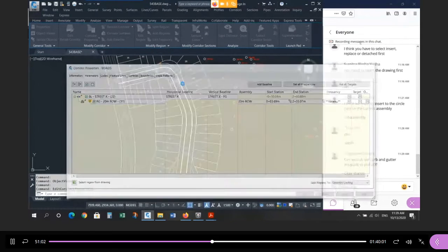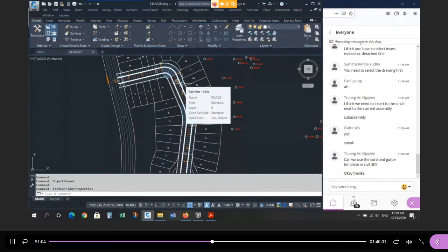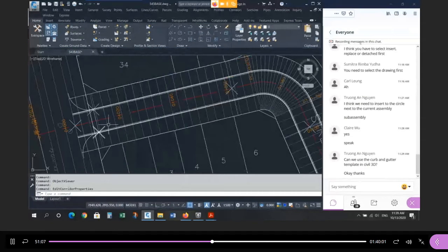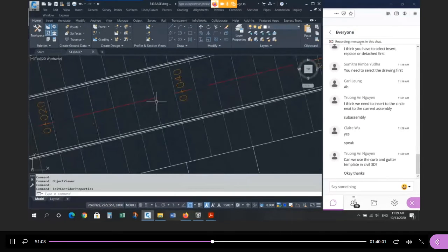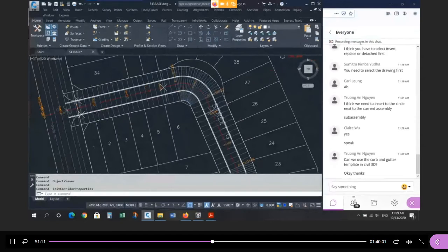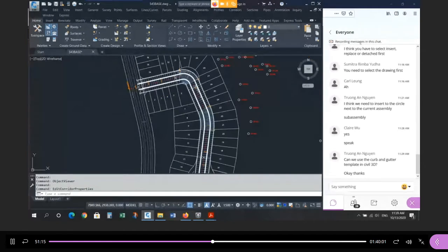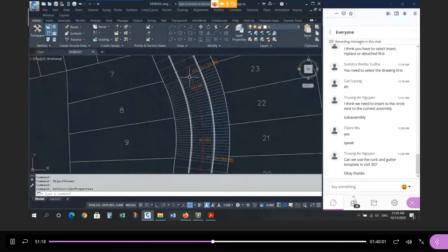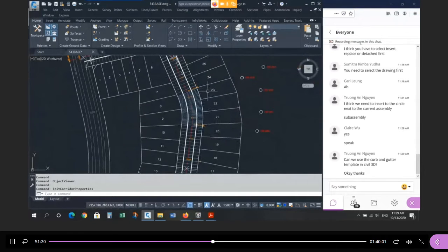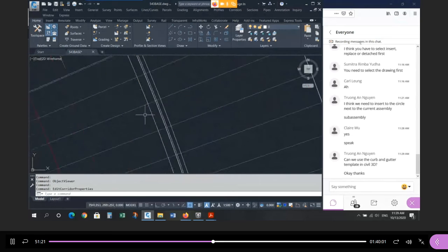It's going to rebuild the corridor, and now wherever you have a curve, you're going to see a tighter grouping, right? So on a tangent, every 3 meters, so the distance between these blue lines is 3 meters, and then when you go around a curve, every 1 meter. So now it starts to look more like a curve, right? And same thing here, I have a curve, so every 1 meter. So at a glance, it looks curved, but if you zoom in, it's a bunch of straight lines.